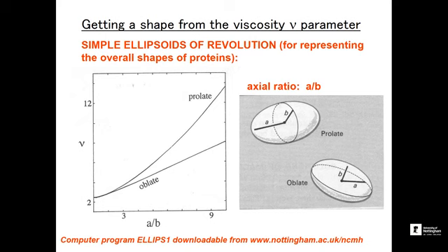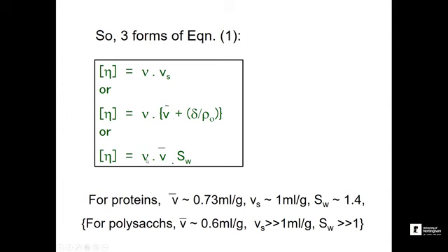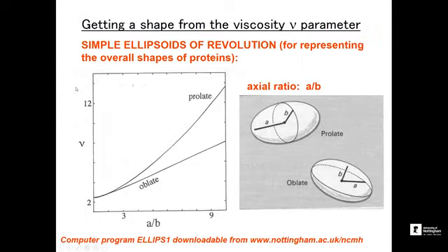Then from the final value of the reduced viscosity, which you approximate as the intrinsic viscosity, or use the Solomon-Ciuta equation, and using the value of the swelling from the first part, you can work out the new value of nu, and then either read off from the graph or use the computer program.